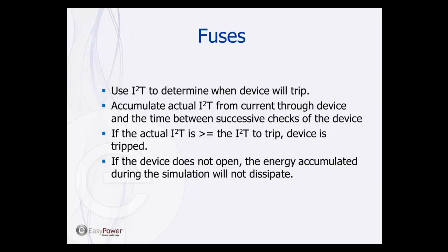Because in the short circuit, if you're using the momentary method, basically we look at the momentary current, view where it sits on the TCC curve, say it's 10,000 amps of fault current. If you look at the TCC curve, it says it trips in 0.25 seconds. Then we use 0.25 seconds to calculate the arc flash incident energy. However, we're only looking at it for a short amount of time, in this case a half cycle.